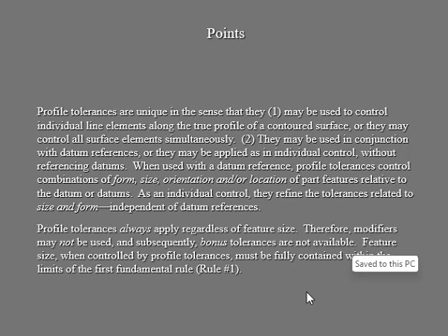The same is also true for your profile. It doesn't matter whether they are orientation, location, or profile tolerances. We're going to follow about the same rule, repeating again and again. So for profile tolerance, you're always going to apply RFS. So when you study, make sure to take notes, put them in your own notebook, and try to write them out and compare them, so you know which one is regardless of feature size and which tolerances you don't need. Write it down one by one.